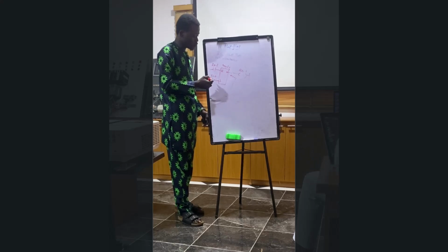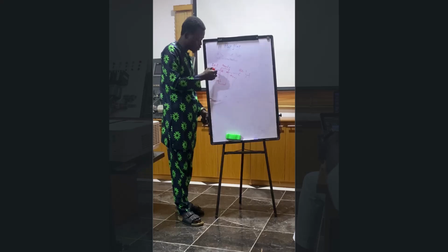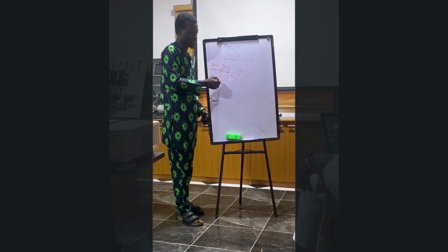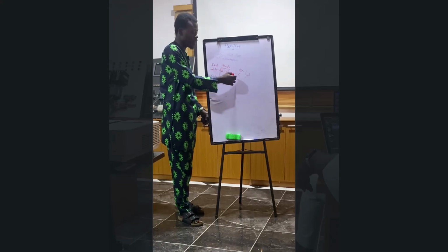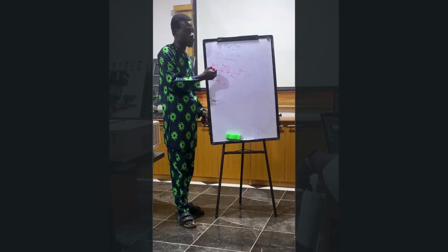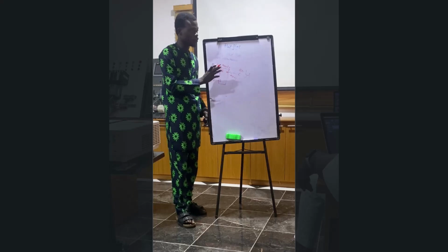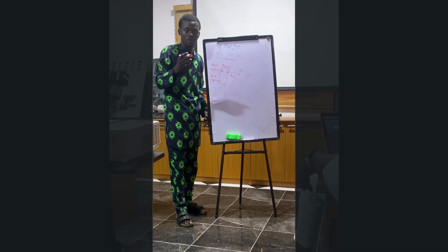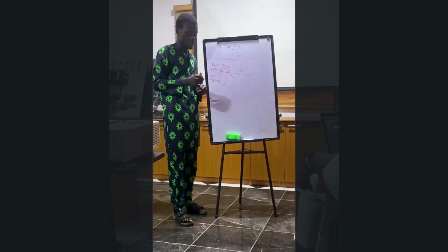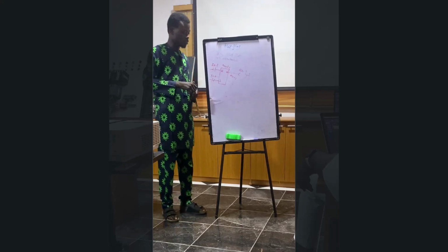But in a situation where there is signal at these two states, that is, you press both your I0.0 and I0.1, the set dominates, meaning your RLO will be what? Will be 1, irrespective of whatsoever is going on with the reset here. Are we together? So basically, that is how flip-flop works. So let's try that out in the software, TIA Portal.